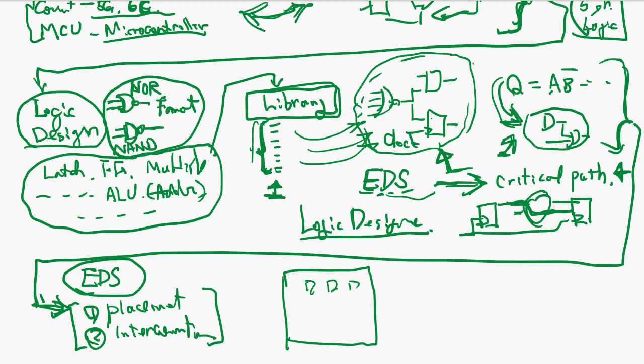How do you determine optimum? Well, it depends on where you put things. If this module interacts with this, you put them close, right? So the interconnection can be minimum. You don't put this and this far away, because there are so many wires going back and forth. And placement and interconnection. Interconnection may use multiple aluminum conduction layers. And between the aluminum conduction layers there will be silicon oxide for insulator.